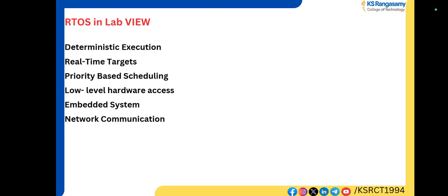Then real-time targets. We can deploy LabVIEW code to real-time targets, including CompactRIO, PXI systems, and real-time enabled PCs. Then priority-based scheduling. LabVIEW RTOS uses priority-based preemptive scheduling to ensure high priority tasks get CPU time. Configure task priorities to manage the execution order.